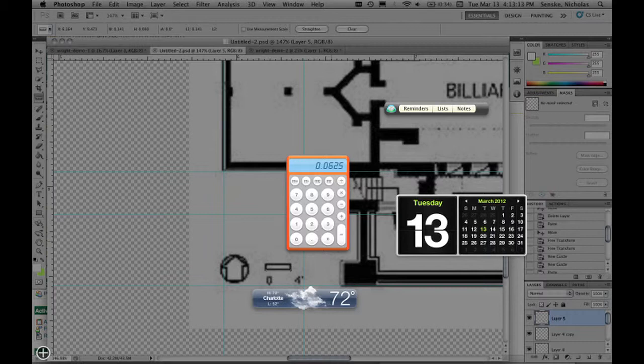So let's go ahead and divide that, 0.0625, divided by 0.03525. Okay, and that gives us 1.773. That's the scale factor. We need to scale the drawing by 177.3%, and that will make it 1/16. Okay. Once you've done that, if you want to make it an eighth, you could scale it by 2. You know, make it a quarter, you could scale it by times 4.